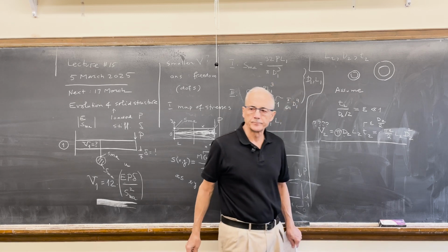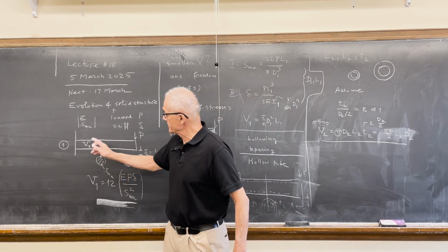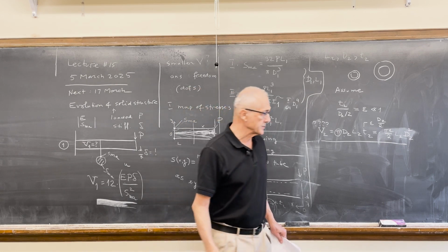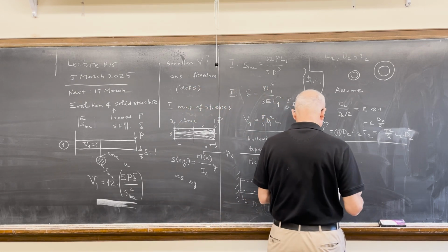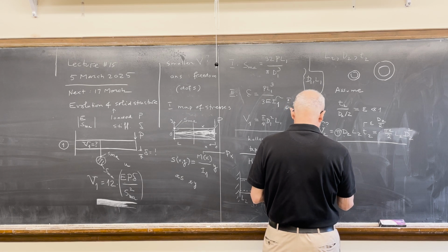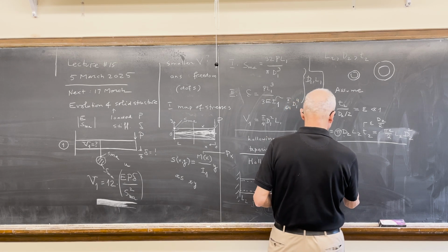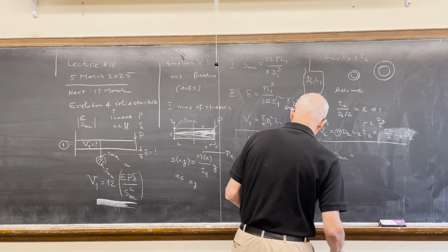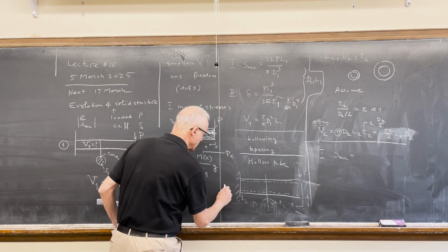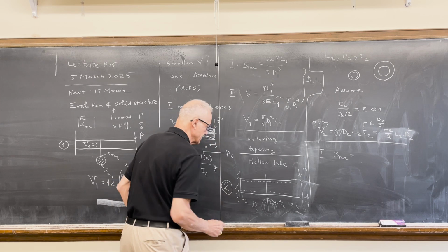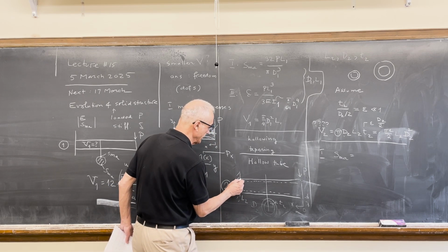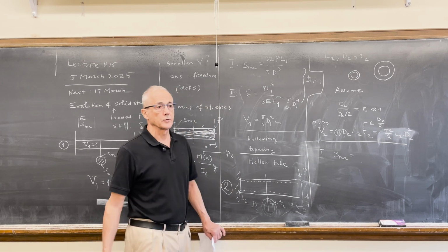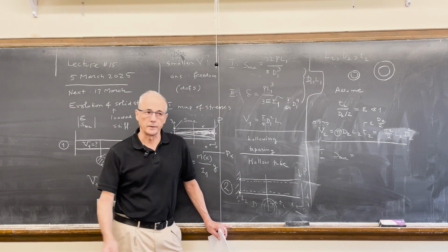The one that comes from the distribution of stresses, called the Roman 1. And I'll just write it down the way it is in the textbook. For that, we get that the maximum allowable stress in this design, just like in the first one, this is design number 2, will happen at the north pole and south pole of the cross section that touches the wall.